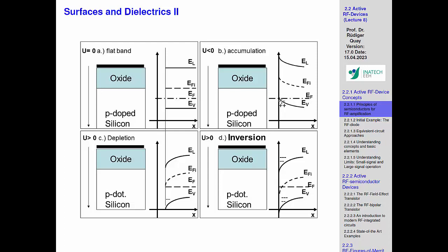So let's assume for the moment we have a p background doping, which accumulates the holes now by bending it up. So the valence band also bends up if we just take a negative voltage there, so the holes are attracted. That is kind of reasonable. Yeah? That's something which is not really difficult to be understood.